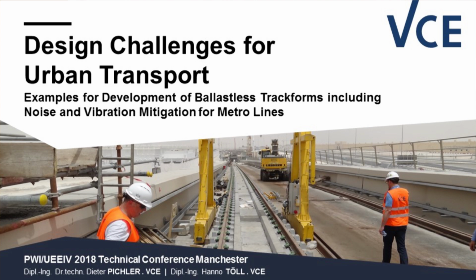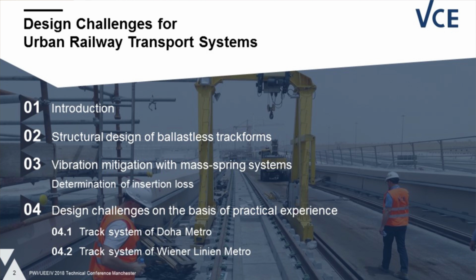Our presentation has the following content. After a brief introduction, I will talk a little bit about structural design of ballastless track forms. Mr. Toell then will present vibration mitigation possibilities, especially with mass spring systems, and how we determine the insertion loss of such systems. And then we come to some practical experience. We show two examples. One is the track system for the Doha Metro system in Qatar, which will be under operation next year. And the second is an example of the track system of the Vienna underground system.